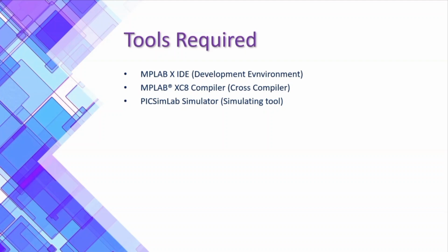There are three major tools which we are going to use in this project. First is MPLAB X IDE, which is a development environment. This tool is used to program the microcontroller, and the second tool is the MPLAB XC8 compiler. The program which we write in the IDE, the XC8 compiler compiles that program to run in the microcontroller.